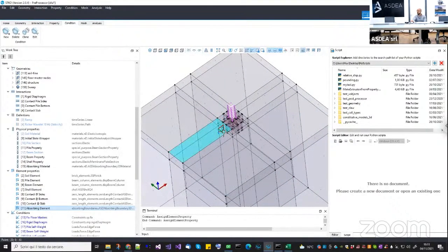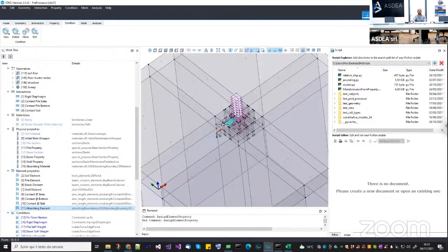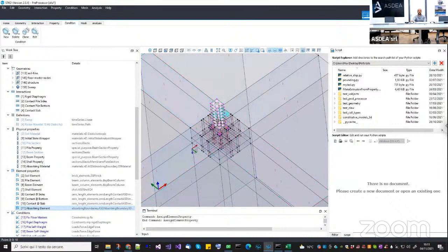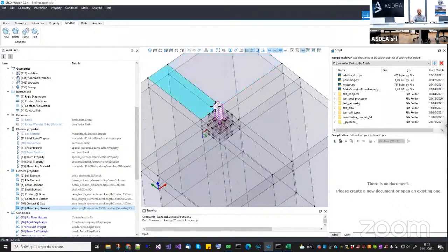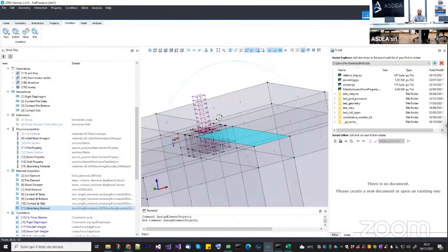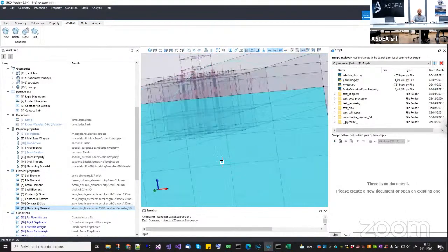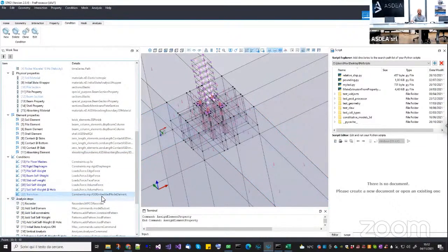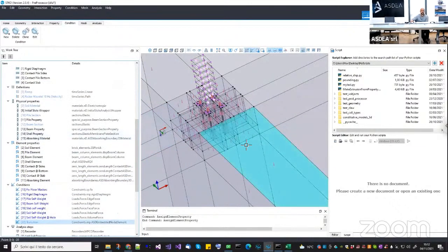The only thing that is missing is the connection between the detailed model and the surrounding soil, because now my model will be singular because the inner domain is completely detached from the outer domain. Now I need a way to connect them. Due to the incompatibility of the mesh, but also of the geometry, I need another way to connect them. And this can be done through this transition constraint, which is the embedded node element. Okay, how can you do this?